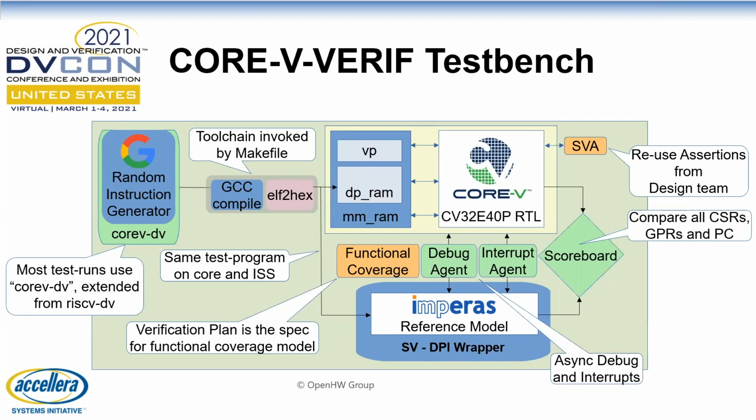We've also done a lot of work with functional coverage, of course, sampling what instructions we're running to ensure that we're hitting the entire ISA, as well as a lot of assertions and checker models that we've written to verify external functionality, separate, but very important to the ISA compliance. Debug and interrupts are a couple of examples of those, as well as quite a few other assertions.